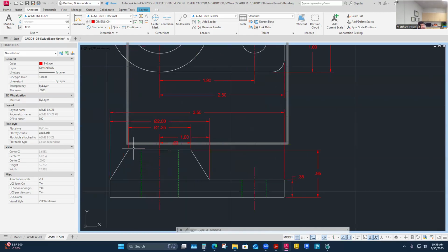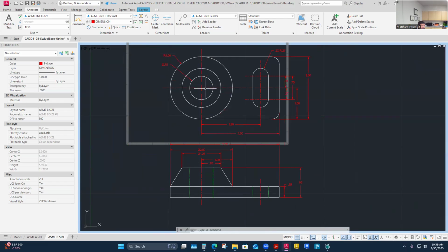I could go either direction, really. It wouldn't matter if I went this way or that way from the center, I don't think. If these were the other way, I don't feel there's a good or better there. I just plopped them down, but I think I'm going to keep them. This one I've located, so I don't need any other dimensions there. I haven't really established any new datums. I've got the bottom datum, and then the crosshair datum controlling all the other dimensions. They're all associated with those 3 points.